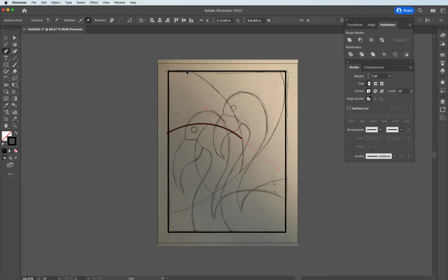I can move up to the top, even though again I'm running past the border. This will allow me to get as accurate as possible to make sure that I get a bend that follows the overall look and feel. Again, I do want to make sure that I am getting the overlapping black lines. So you can see from the first line I originally drew, I'm making sure that the red appearing as representation of my line is intersecting and overlapping into the original first line. Again, I can hit escape to end my line.